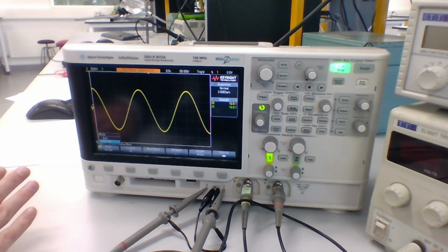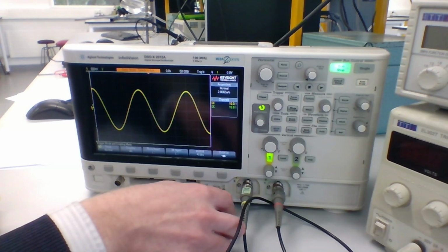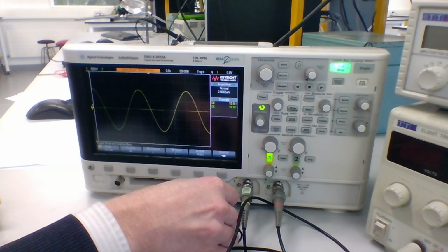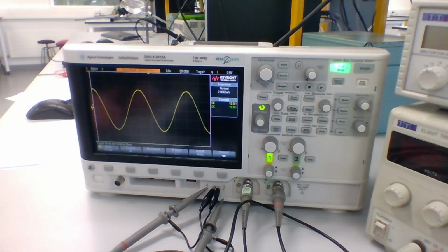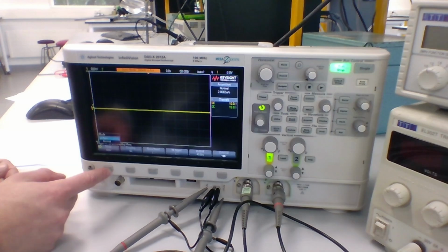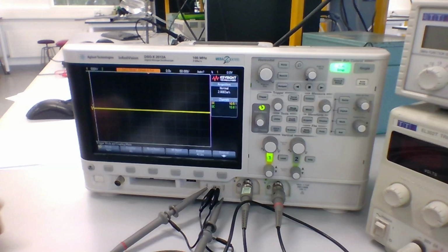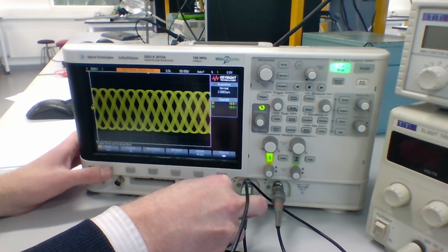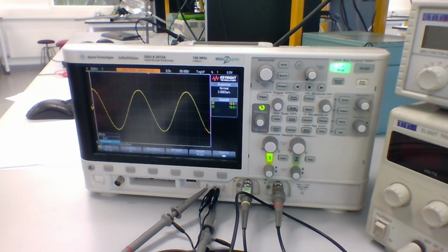If I do that, at first nothing seems to change. But if I now disconnect the oscilloscope probe again, like I did before, if I'm careful with it, you can see what we measure is the last thing that we captured on screen. In auto mode, if I change back to that, it's constantly taking measurements, and so it says, right, well, I'm measuring nothing, so display nothing. But if we're in normal mode, it retains the last thing that was actually measured.